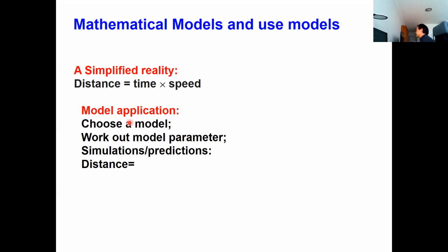But for this semester, semester 1, all of you need to choose the Cam-clay model for your simulation. So for the first semester, choose the model and be able to use it to do your simulation, because it is the simplest one. It is the basic one. It is the most popular, most widely used model in our geotechnical engineering practice and theoretical research.